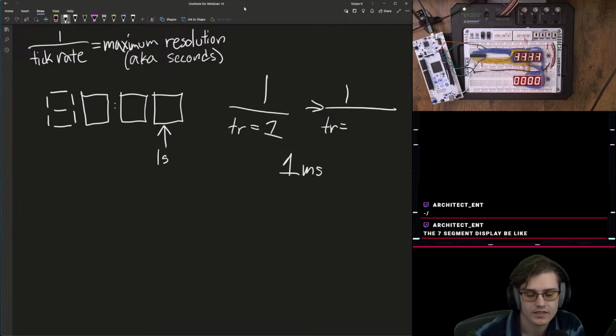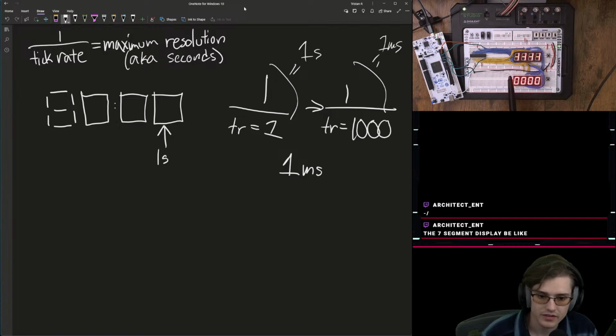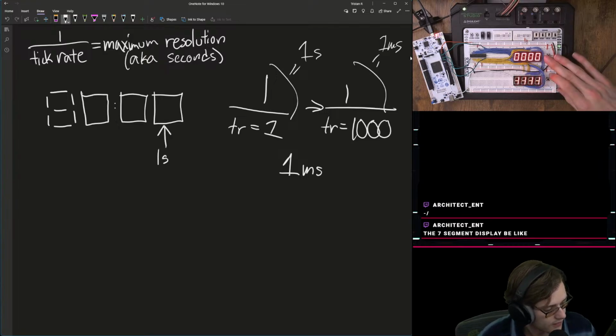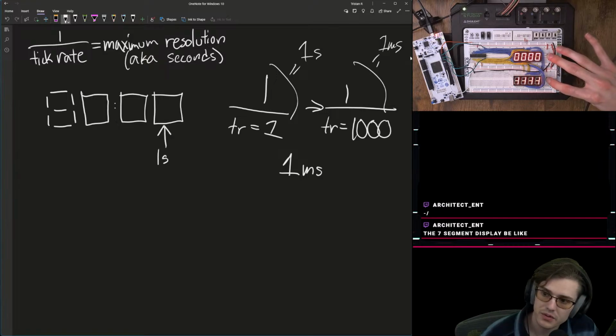We'll do that. Okay, so back to it, right? This equals 1 second. If we're gonna do 1 millisecond, we need the tick rate to at least be 1,000, which is the same as 1 kilohertz. So this would equal 1 millisecond, right? Easy peasy. It would allow us to move really fast because I don't really see anybody moving faster than 1 millisecond.